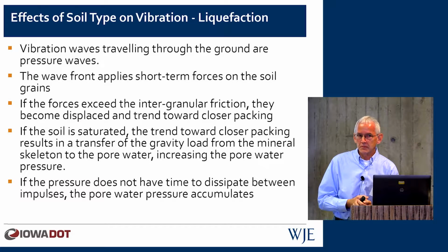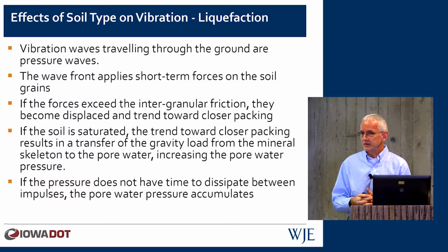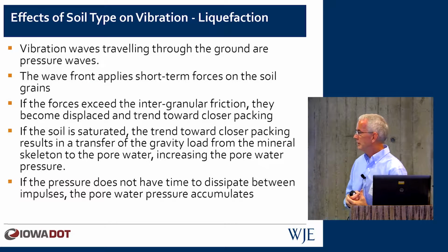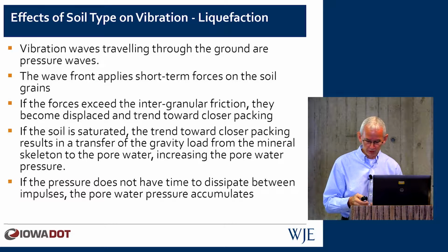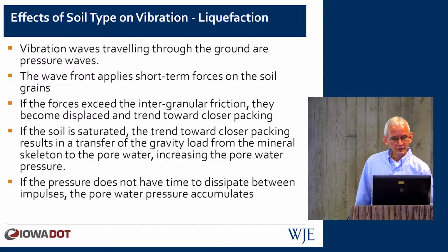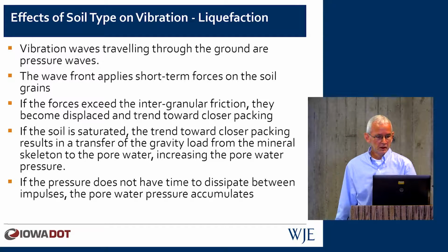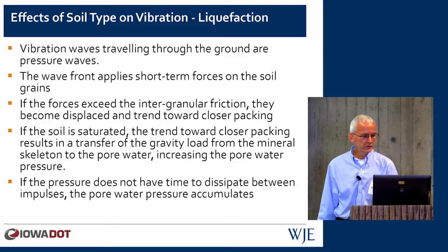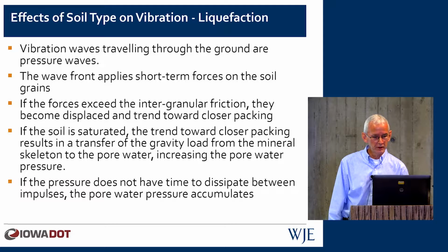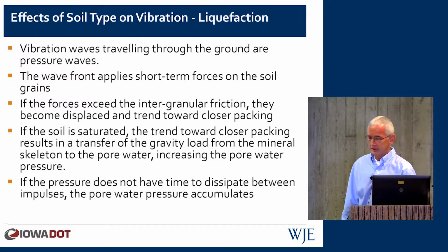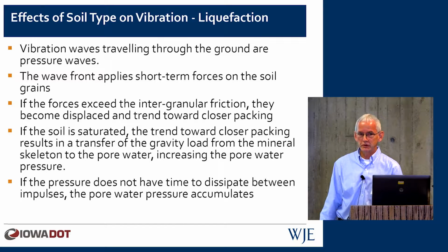Sometimes in consolidating soil or doing compaction work on soil, you may add some moisture because it helps lubricate the soil, it helps it to come together. You wouldn't necessarily do it on a saturated soil for various reasons that may become evident. If the soil is saturated, the trend toward closer packing results in a transfer of the gravity load from the mineral skeleton to the pore water. That tends to increase the pore pressure.